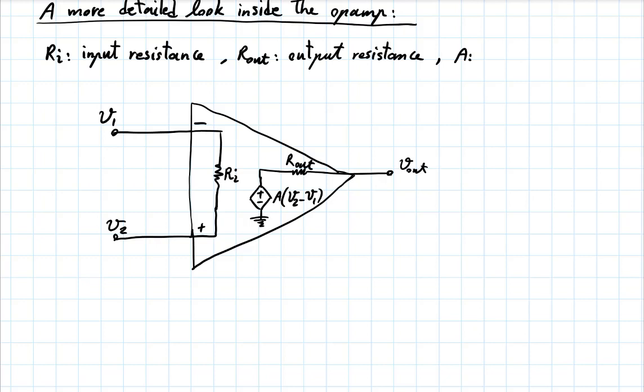More specifically, it's called the open loop gain. For reasons that we'll talk about briefly in this course, this is called the open loop gain. But what matters primarily at this point is that it's called a gain. It's a very, very large number, a large value. And it's dimensionless because it's a ratio of two voltages. It's a voltage-controlled voltage source.